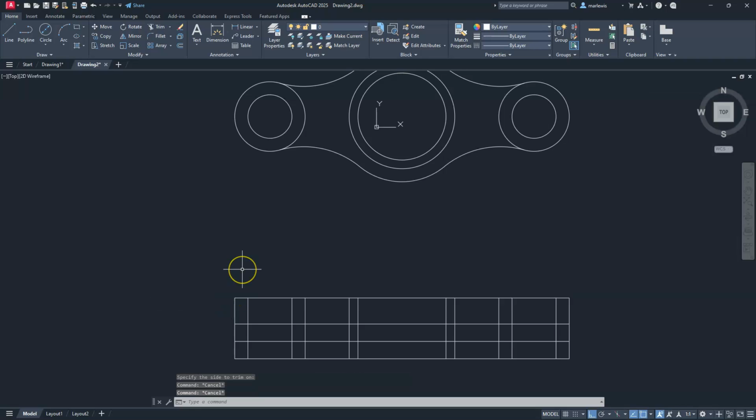Okay, so all of that is done. I have my shape defined here. All I need to do now is just finish trimming all of this out and everything should be here. So let's go ahead and use the trim command. We know that this big part here is in the middle, so I'm just going to trim off these lines here. I'm just going to run a line going straight across here. Likewise here, so I'm just doing one single click there and come across. That's going to allow me to come back and erase this line here as one total unit.